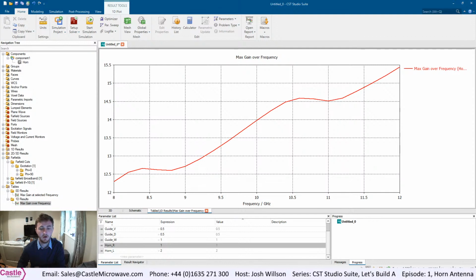We'll now go into co and cross polarization. The co-polarized Farfield component has the same polarization as the excitation, the y-oriented in our case. The cross-polarized Farfield component is orthogonal to the co-polarized component and main lobe direction. In order to use different polarizations for transmitting and receiving data simultaneously using the same propagation channel and the same frequency, an antenna design goal might be to maximize the co-polarized and minimize the cross-polarized component.